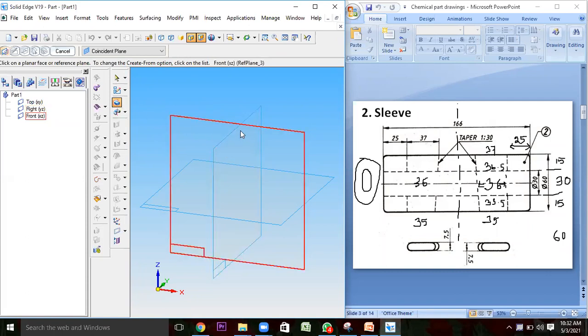Otherwise, if you create it in one single dynamic edit, and I want to change the dimension of this cylindrical rod but I don't want to change the dimension of this cutout, then we cannot edit in that fashion. But for this syllabus you can create similar concentric circles. But I tell you to create it separately. This one should be created separately, and after that this cutout should be created separately. We'll see the method. Okay, that's how to create that protrusion.